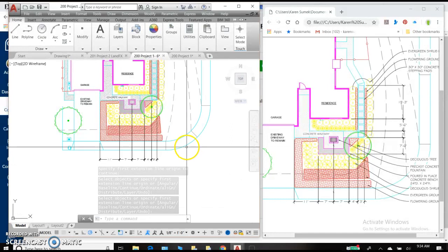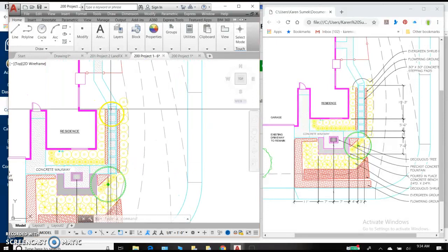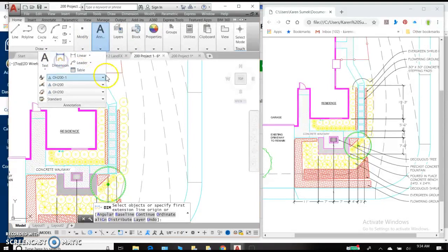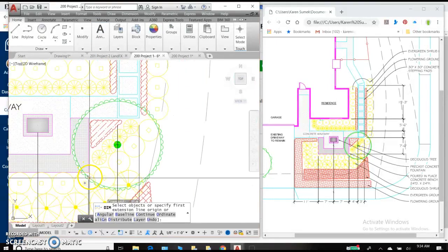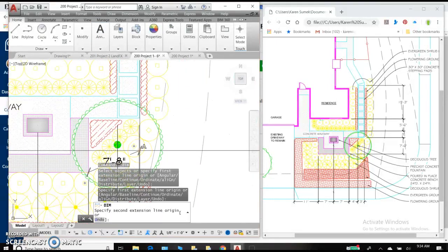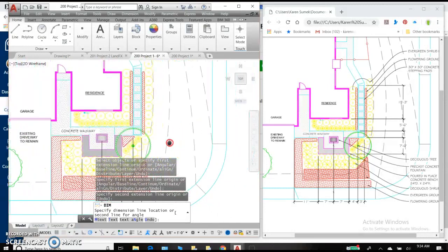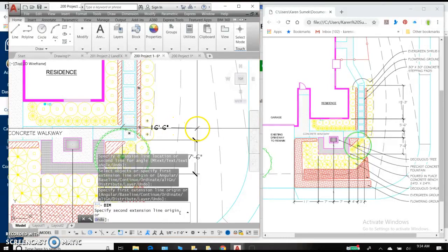Close that. Okay, to go in the opposite direction. Zoom in a little bit, and again, dimensioning our quick dimension. And we can start at this very end point and move to this end point and drag that off until it's not conflicting with any information on the plan. Use our snaps to select the endpoint of that.